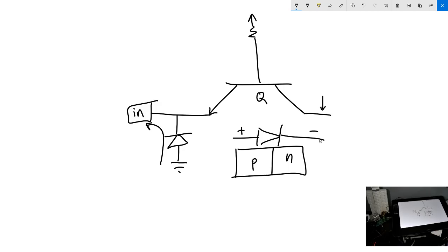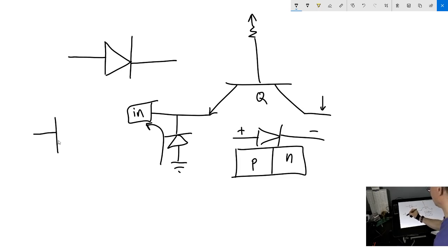By the way, here's a little trick that I love to talk about. Which is the anode and which is the cathode? I could never remember. But if you look at the symbol for diode, maybe if you turn it around, see how there's a K over here?